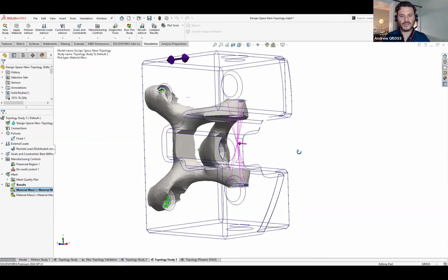So what would be the next thing you could do from here? Well, I can right click and export a smoothed mesh, right? It can either be a configuration or a completely new part file under advanced support. Now, this is stuff you would explore on your own if you're interested, but this is where I can create a solid body or surface body or just a graphics body. And that's what it's going to spit out, right? Say I just have a solid faceted part. Again, not a finished geometry part. And what we would do from here is open that in its own file.